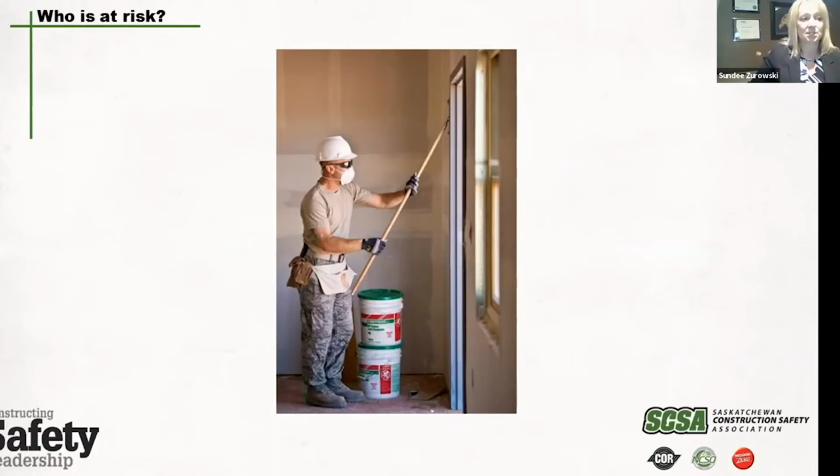In addition to lower exposures, vacuum sanding can help the sander, subcontractor, general contractor, and building owner in other ways. The dramatic reduction in airborne dust exposure results in a much cleaner work area during and after sanding. For workers, the clean working environment is more comfortable. It's less irritating to the eyes, nose, and throat, and is less likely to require respiratory protection.